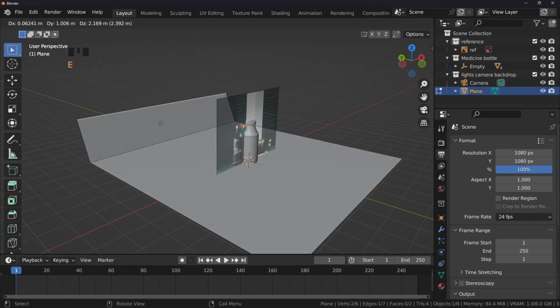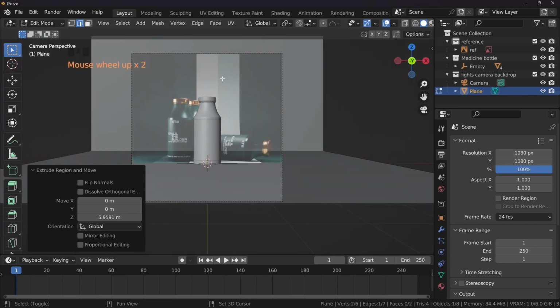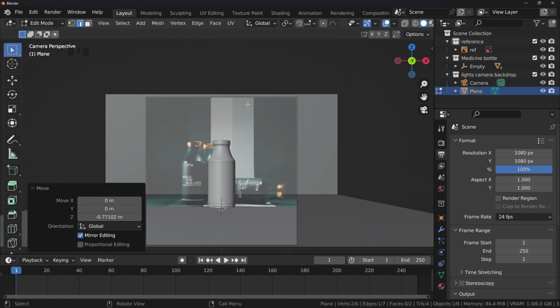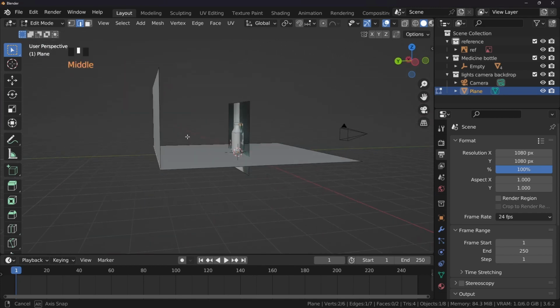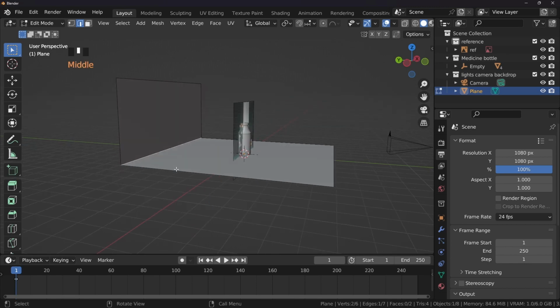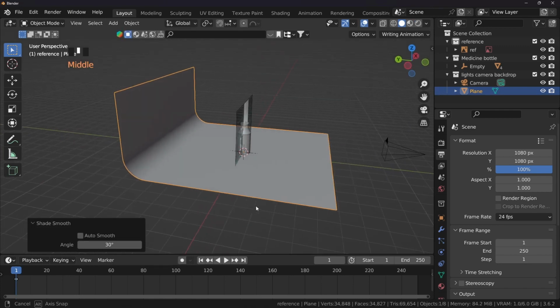Now we can select it and extrude it, and it is extruding something like this, but we need it straight, so press Z and one more time 0 for the camera view and put it a bit down, just up to here. It's fine, it's great. And I need this area to be a bit rounded. This is not round. So there are a lot of things, like you can press Ctrl B and increase the segments, and Tab out, right click, shade smooth, and hooray.